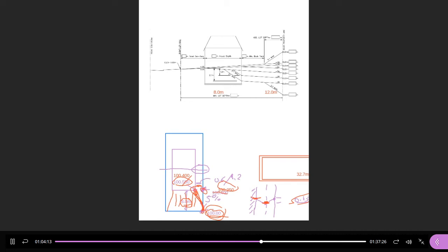Anything in between would be a split drainer, right? Let's say the difference between the front and the back were 0.75. You'd be between 0.98 and 0.65, which means your front drainer would be 2-point-something%, steeper than the minimum and flatter than the maximum. So any difference between 2 and 3%, or 0.65 and 0.98, between the front elevation and the back elevation, would be a front draining lot with all usable backyard with a minimum slope of 2, maximum 3%, somewhere between 2 and 3. Everybody understand that?